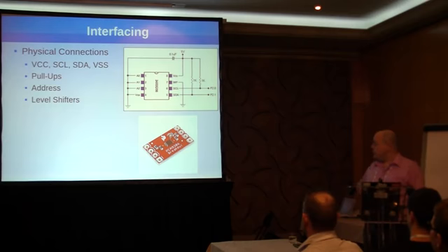Now if you'll notice on this particular breakout board, there are 4 resistors on each side. Those are actually the pull-up resistors that we just discussed. So this level shifter actually includes the pull-up resistors for you. Now, when you talk about doing a design or plugging these in, you have to make sure that your SoC or device doesn't have multiple pull-up resistors in different locations.